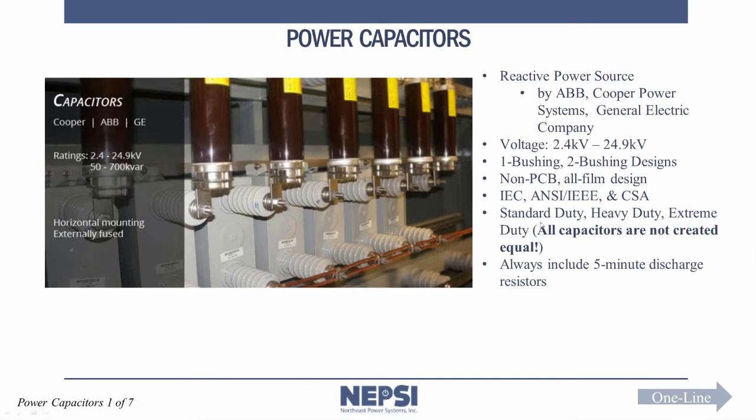Also, capacitors can come in as standard duty, heavy duty, or extreme duty. All capacitors are not created equal. That's the key here. It is important that if you're specifying a capacitor, you understand the capacitor that you're going to get. Or if you're evaluating a specification of somebody who has quoted you a capacitor bank, it's important to understand the type of capacitor that you're getting.